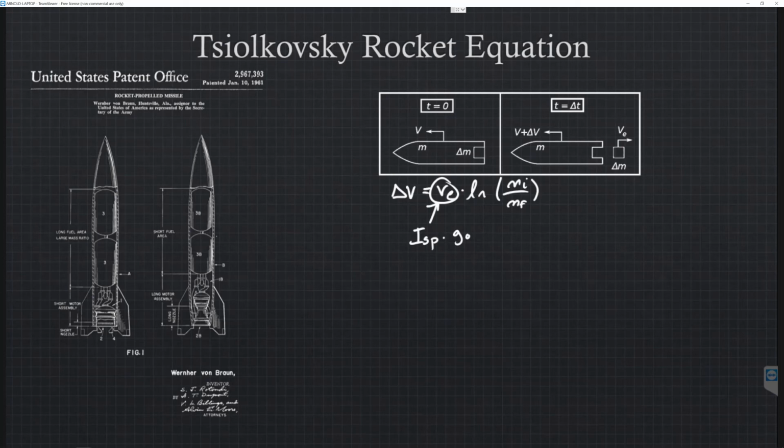If it has a different gravity, if you're in space where there is no gravity, quote unquote, you're still going to apply Earth's gravity to this equation because it's just a simplification for how we can compare different types of rocket engines using specific impulse. And you can think of specific impulse similar to the fuel efficiency of your car, similar to miles per gallon. The higher your specific impulse, the more efficient you are being with your fuel. And this is also a readily available parameter and used for comparing different types of rocket engines and different types of fuel.